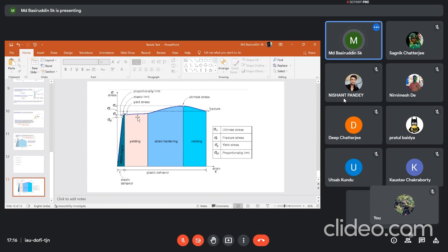So that is why, when that barrier is crossed with a little change in stress, the stress will fall down again. That is why you will find a zigzag area in that zone. If you zoom in on this zone by taking the actual data, you will find that first it will increase, then decrease, then increase, then decrease, something like that.